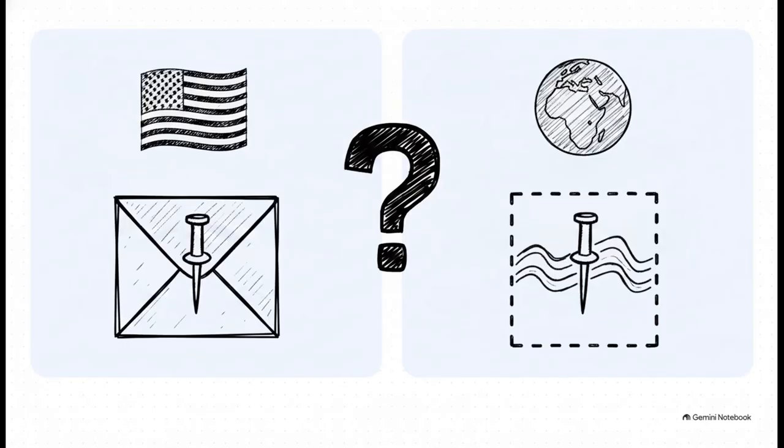So, let's say I hand you a print with a simple tolerance feature. Maybe it's a pin, with a diameter dimension and a basic straightness callout. How do you interpret that? If you're coming from the ASME world, you're automatically going to apply the envelope principle and RFS, regardless of feature size. That's just muscle memory. But if that exact same print was authored under ISO GPS, that assumption is completely wrong. ISO uses the independency principle by default. So, without explicitly knowing which standard governs the document, you literally cannot know what the print is actually asking you to make or inspect. It's wild.